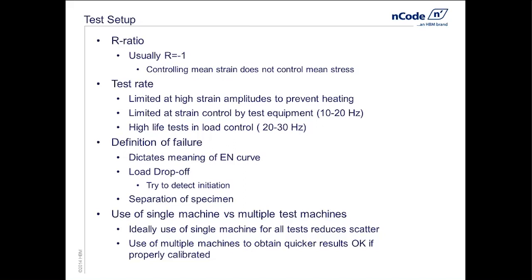Now, as we look at very high cycle strain-life tests, there's minimal plasticity, and we can get away with assuming that load and displacement are the same thing. So you'll see a lot of times test labs will switch over to load control at the higher life regime and allow you to run at a higher speed. So we can at least up the speed of the test for those high cycle regimes and minimize any issues because, again, there's minimal plasticity there. So we can get higher speeds.